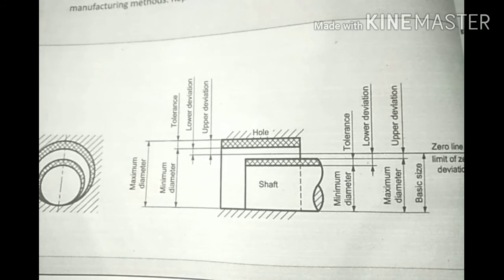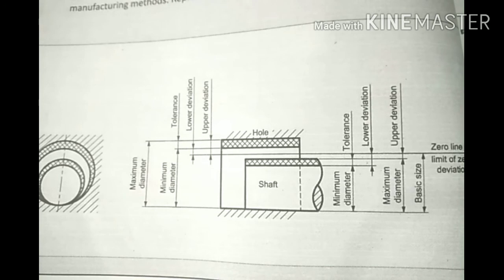Production drawing also gives additional information regarding the name of the company, title of the component, scale used, method of projection, drawing numbers, date of drawing, who prepared the drawing, who checked it, who approved it, etc. These things are included in the title block.